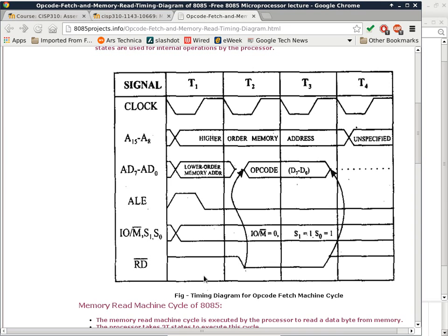Now, if processors are still like this, that means your 3.5 gigahertz processor can really only do 350 million instructions per second, because it takes 10 clocks to execute one instruction. Is that making any sense? But that's really not the case. Modern processors make use of special techniques. Pipelining is one of those techniques, so that they can stack instructions. In other words, you can be doing phase 1 of one instruction, but the other part of the processor would be processing phase 2 of another instruction.